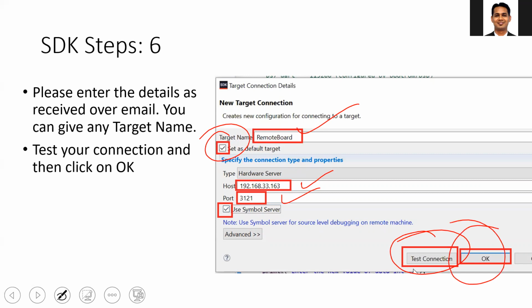After that, you can see that when you create a hardware, we have enabled the UART. On the hardware, we have enabled the UART, but now we are accessing the board remotely. So if you want to see the display on the UART, you need to also access the remote desktop, which is not feasible. So whatever is being passed on the UART from the hardware, we capture that data and then we access it via the JTAG terminal.